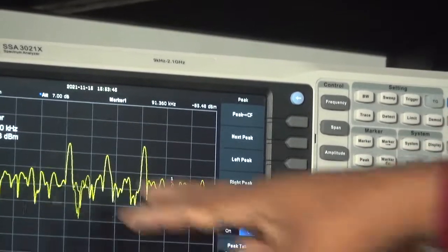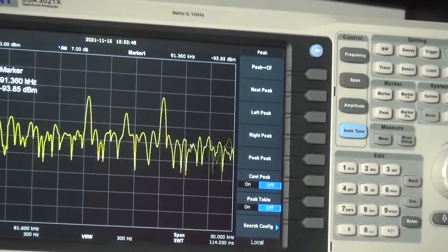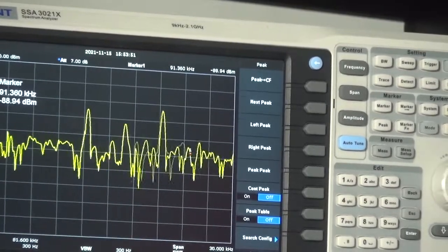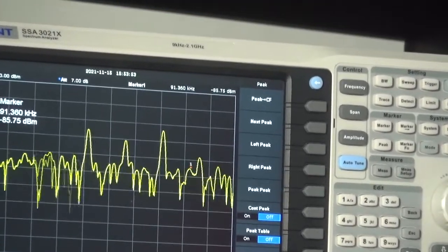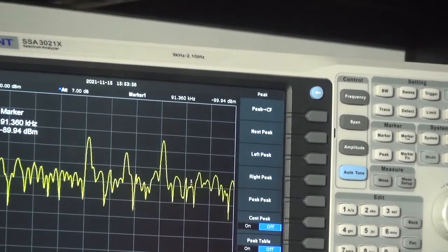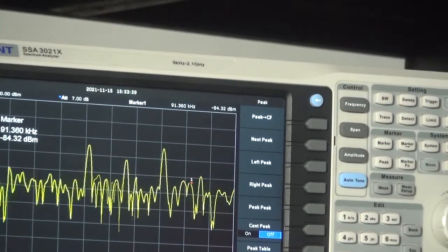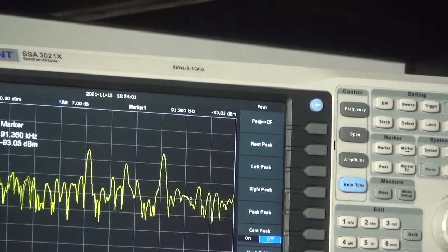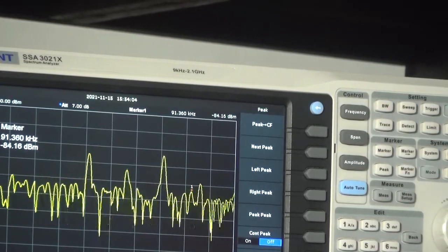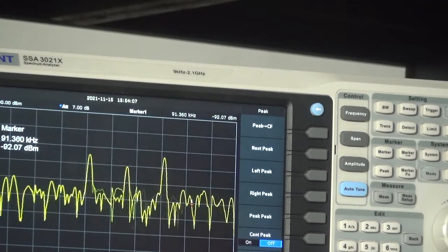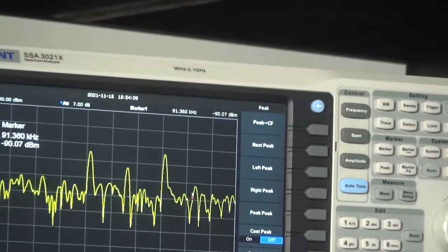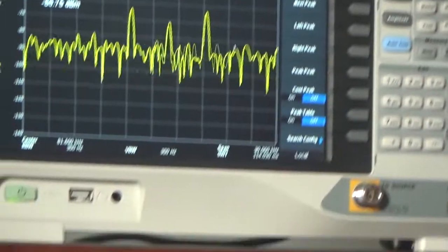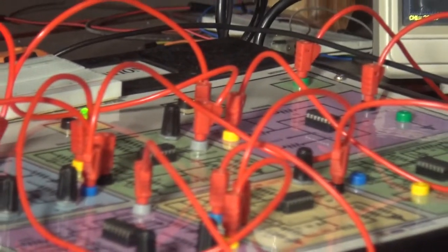So this is actually DSB modulation, dual sideband suppressed carrier modulation. We have implemented this modulator using two modulators. We call it a balanced modulator. So I think you get the idea of how we can suppress the carrier signal, why we suppress it, and how the spectrum looks in this case.